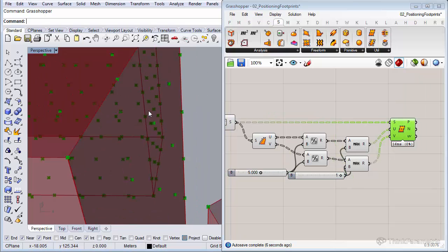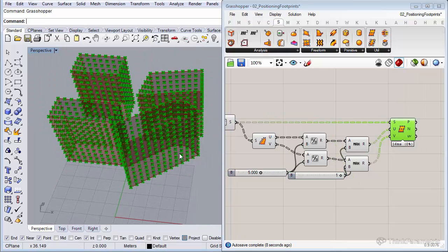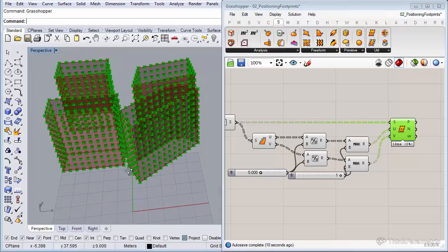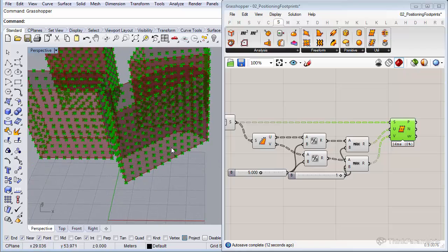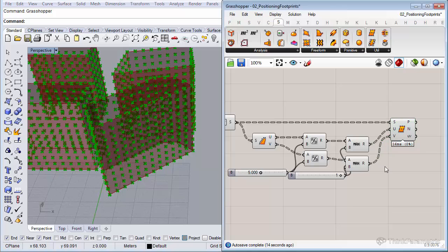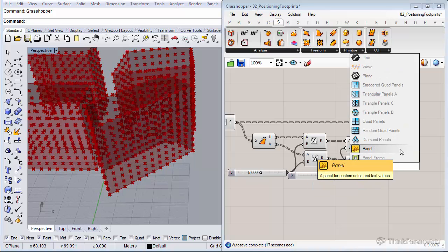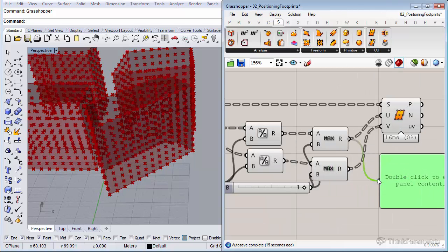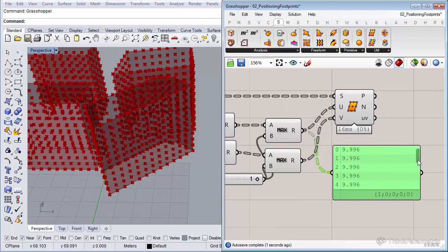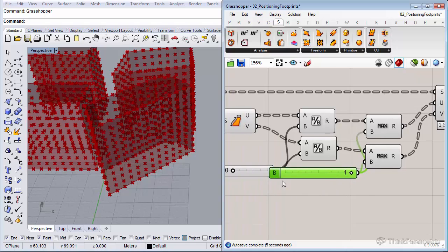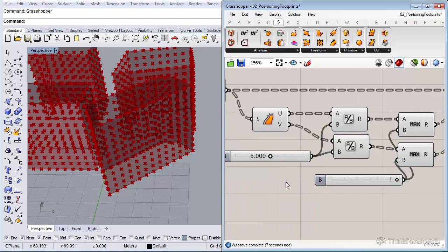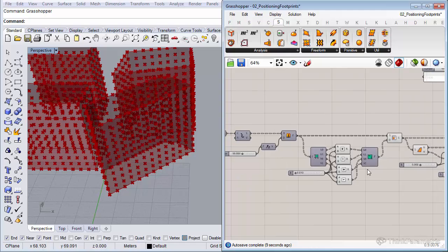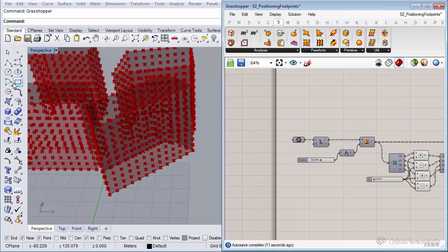Nice. All the facades are more or less equally spaced with a grid of 5 meters. And that depends, because it's going to be rounded off, let's say, if I insert a panel. The numbers will be rounded off. But at least they're going to be around the 5 meters division mark. I can show that to you by just inserting our own rectangle for now, so I can show it to you a little bit more quickly.